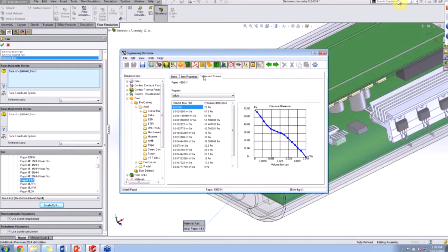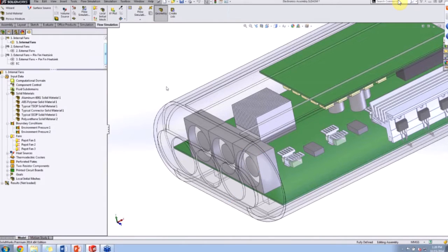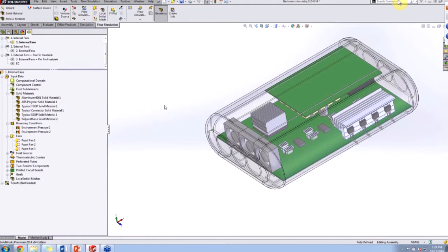If you have something, again, a little bit more custom, we can then reference that, and we can address those volume flow rates with this curve here, right? So what we did was we applied those fans to all those 3 areas here, which is the same fan curve that we're using. So we told the software now how flow is kind of going into the enclosure here.